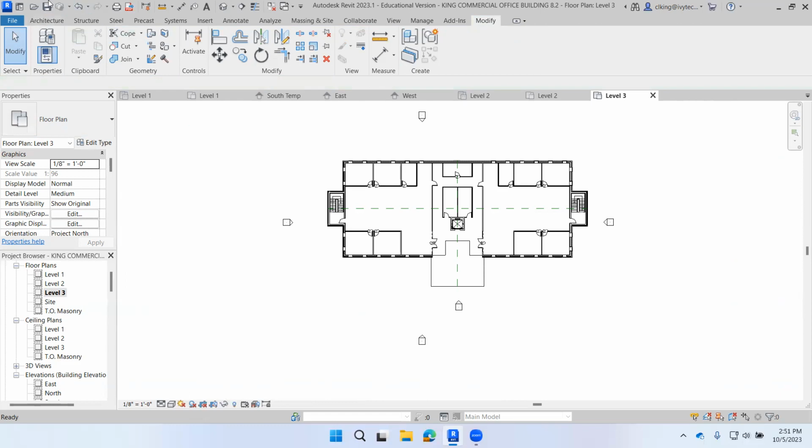Now, I'm on page 8-11, creating and viewing interior elevations. Creating interior elevations is very much like exterior elevations in the fact you use the same tool. The main difference is that you are placing the elevation tag inside of the building rather than the exterior.